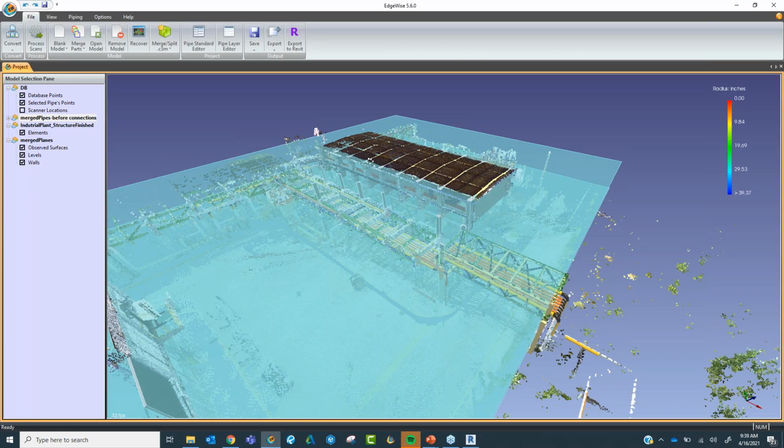So chunking them really is a lot of what I found helps, especially with bigger scans in general: getting them into ReCap, breaking them down into pieces, and processing them. It helps a lot with that. It still gets you the good dense data that you need, but it helps with the processing time as well.